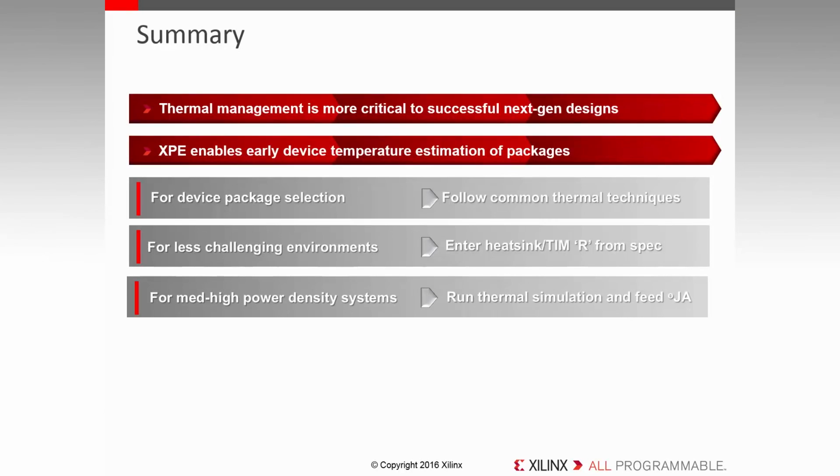For medium to high power density systems, perform advanced thermal analysis using Delphi models to estimate junction temperature and derive junction to ambient thermal resistance. Feed this theta JA value to XPE and analyze thermal and power margin. Take necessary thermal solution and power reduction techniques to keep the device within safe operating conditions.